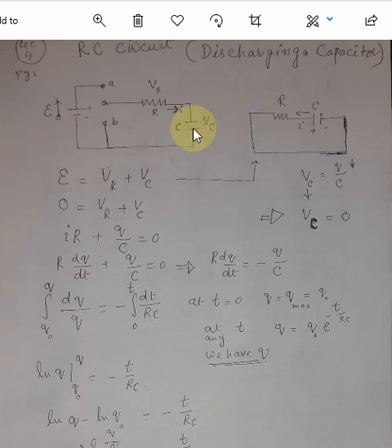By opposite I mean that in the charging process the current was flowing through the resistor in this direction, and after disconnecting this source, the capacitor will discharge through the resistor R in this direction, that is the current through R will flow in a direction which is opposite to this initial direction. So you must keep this in mind, and now we proceed further to calculate the current.